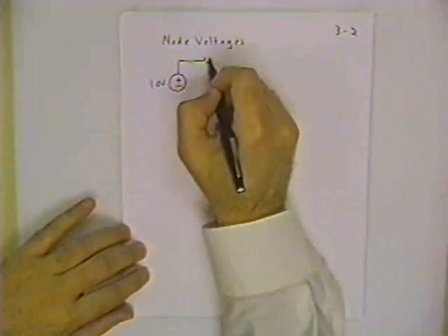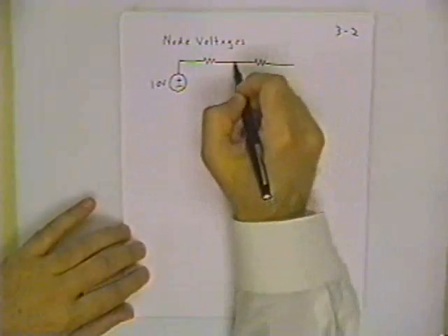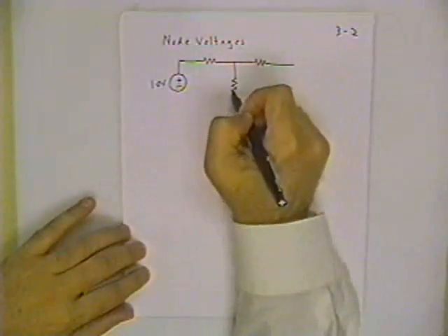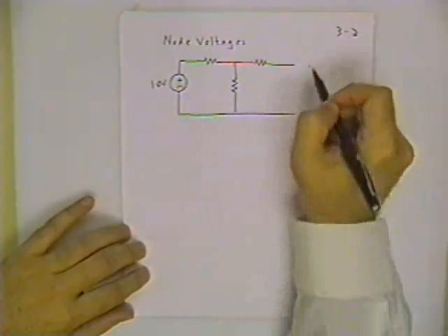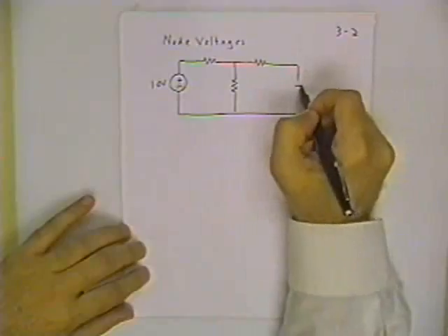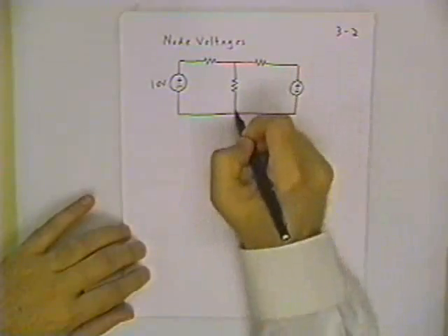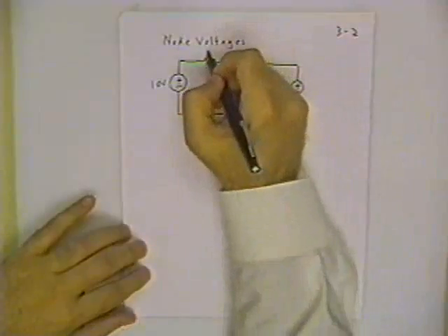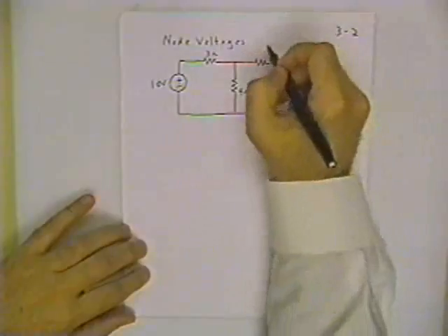One thing that should be pretty clear is regardless of the solution technique you use, you should get the same answers. When you have the luxury of a lot of time, that's really the way to figure out if you've got a circuit solved completely and correctly: check out all the Kirchhoff laws, and then once you've finished with one technique, go ahead and solve the circuit again with another technique, and make sure you get the same answer.